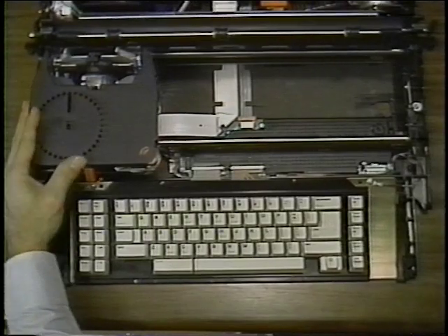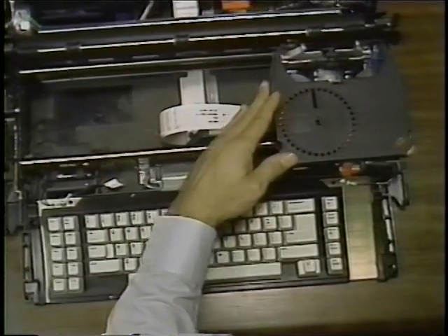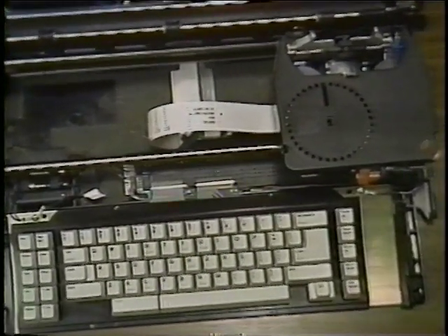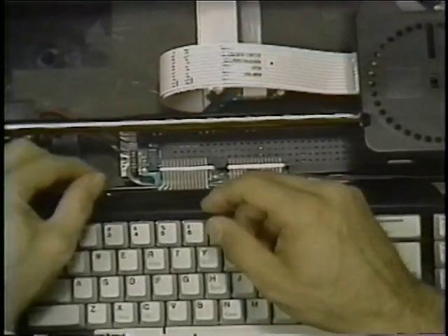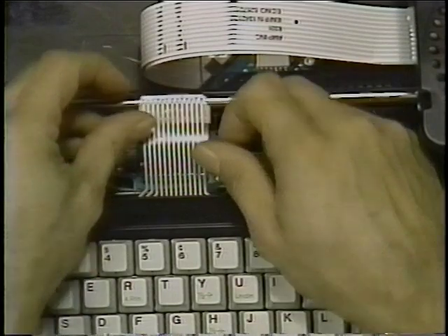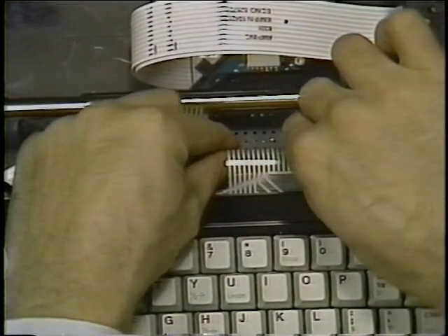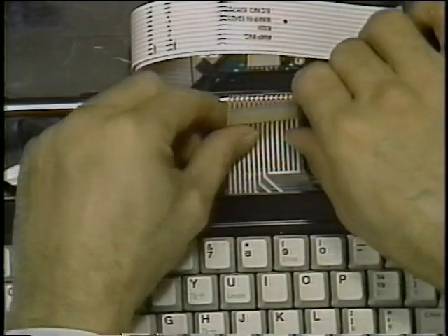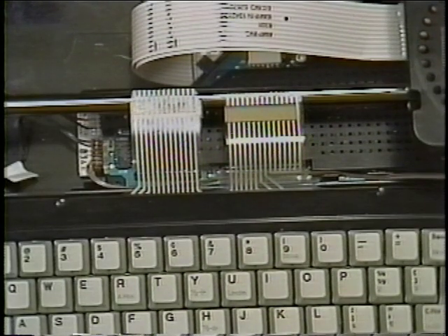To remove the keyboard, start by moving the carrier to the right side frame. Disconnect the drive line connector J1F by grasping the printed circuit membrane just above the connector and gently pulling it straight up. Disconnect the sense line connector J2F from the function board.